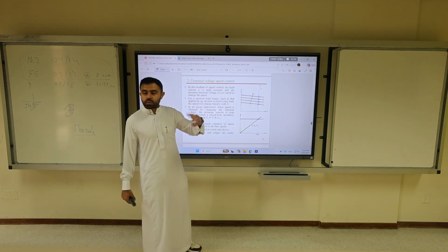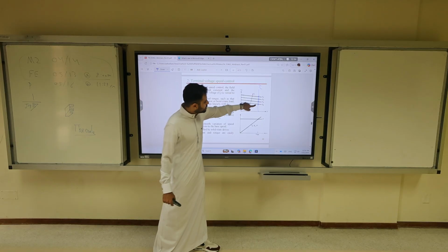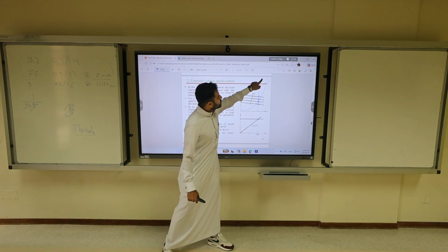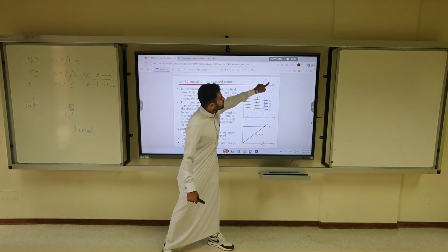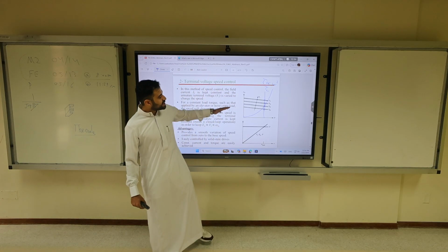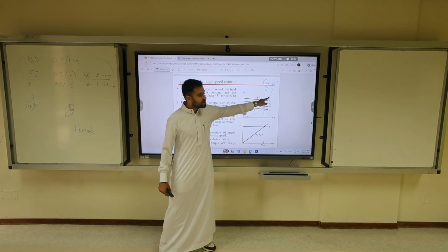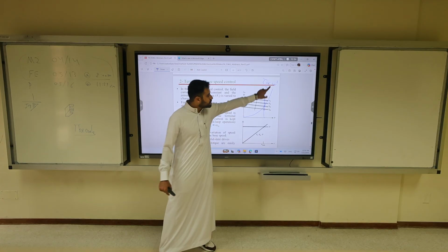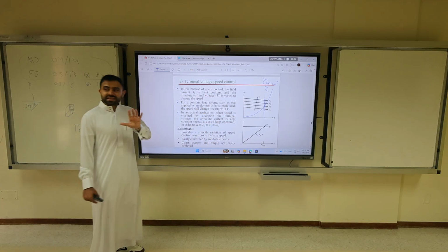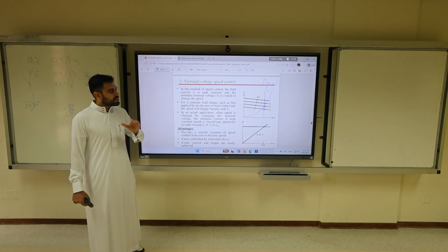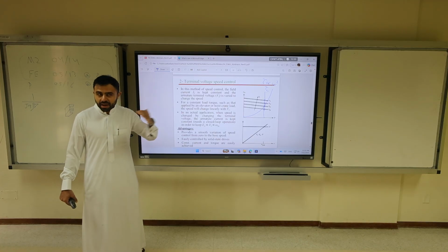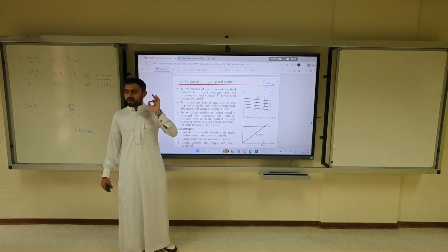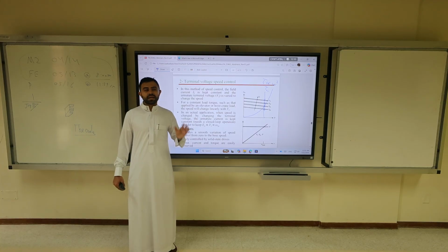For a load torque proportional to omega squared, it looks like that, it's different. This is omega square. TL is proportional to omega squared, like a fan. It's not linear. The curve is different. You see the difference? This is non-constant. It's not linear. The speed will follow the path of the load. Always your speed is where your load intersects, same as the induction.